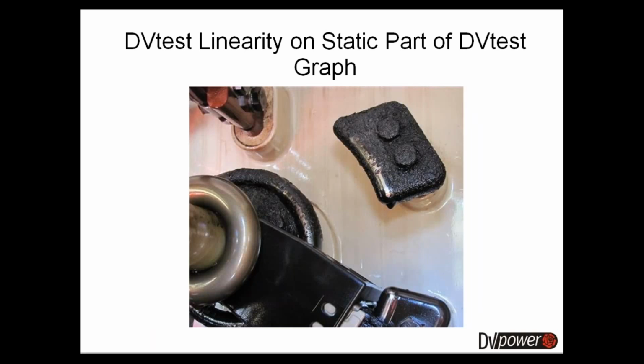So what this would actually look like on a real tap changer is something like this. You have the moving part which goes from stationary contact to stationary contact, and if it encounters a burned and coked surface such as this one, instead of sliding over smoothly, you will see a roughness on the graph such as the one we saw on the previous slide.